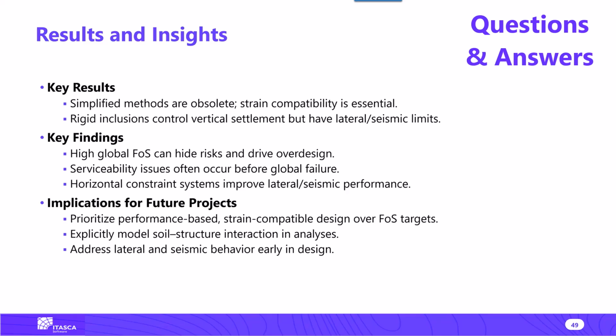if we're talking about the rigid inclusion, those are essentially elements that can take axial force, bending, and shear. So the selection of the structural element follows the idea of what kind of stress resultant is the most important one. For example, for the geogrid, I don't care about what kind of bending moment could happen in a node of the geogrid. That is completely irrelevant. So a geogrid is modeled with a cable element, okay? Because I'm only interested in the axial component.